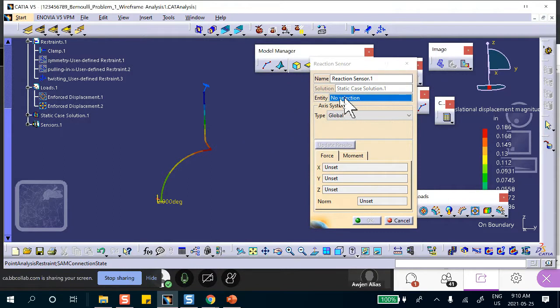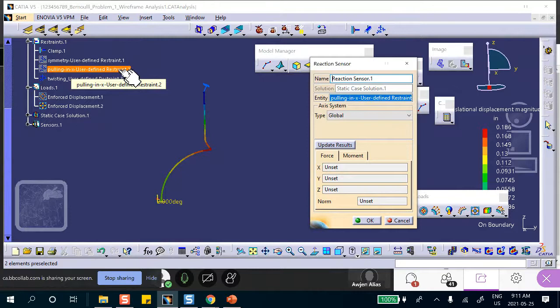Okay, now, so this one, let's see now. Pulling towards us, that was this, right? You click on it. This was pulling towards us. And you update, it tells you that you have 98 pounds multiplied by 2. Don't forget that. 98 multiplied by 2, because this gives you the force needed for that model on the top. We didn't model the bottom piece, so you need just as much for the bottom piece, so multiply this by the 2. Don't forget that.